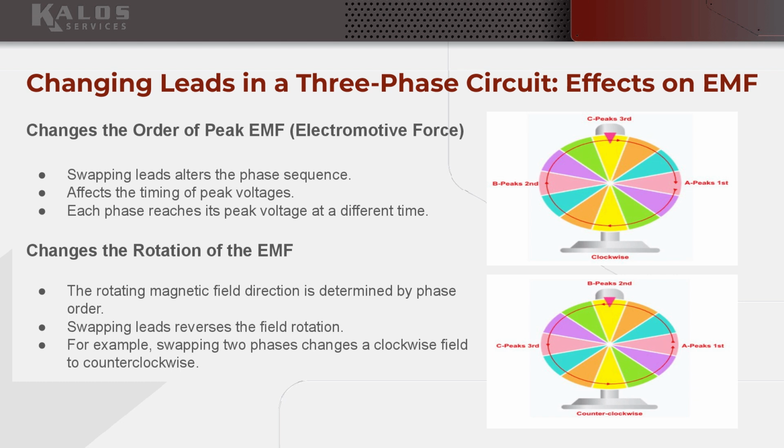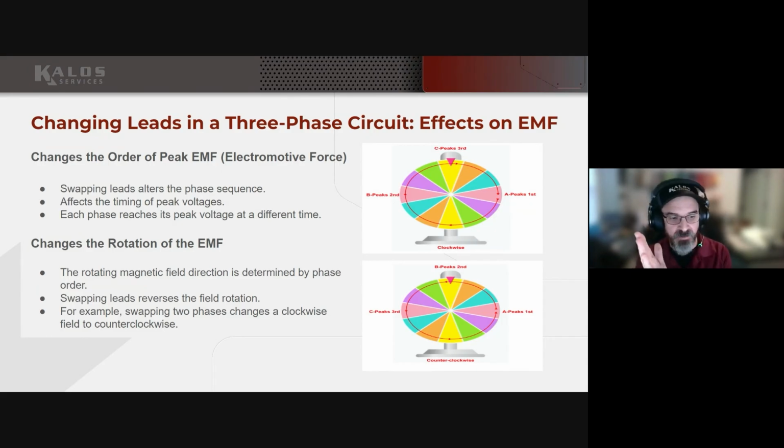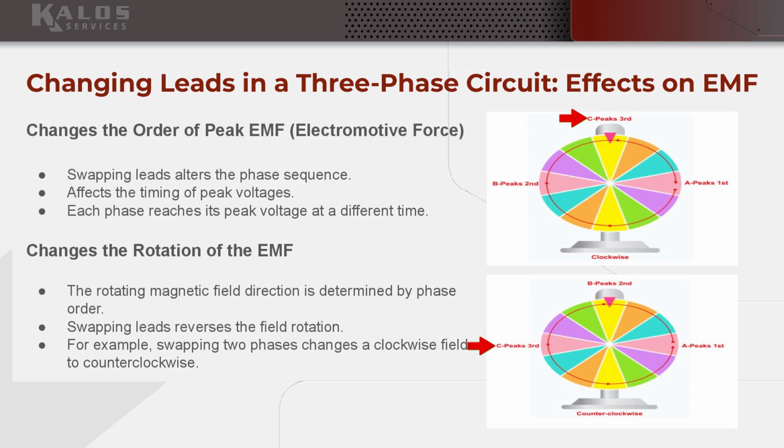Actually, in the stator, the phases change a lot closer to each other, so you're not going to get that much movement. It's going to pretty much just move and stop, more or less in between these two phases, because it's going to find that equilibrium between the magnitude of the two phases and then just pretty much stop. It's not going to keep moving. So what that third phase does is it allows this motor to overcome the inertia enough to keep moving. And as it does, it's going to build up speed.